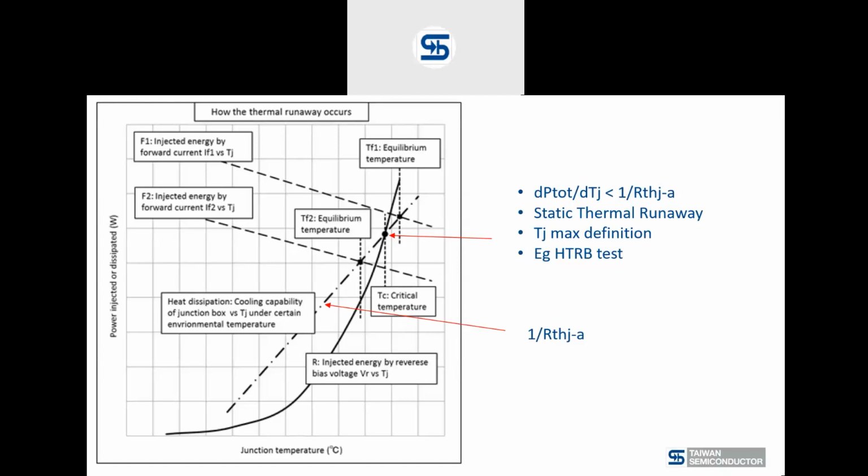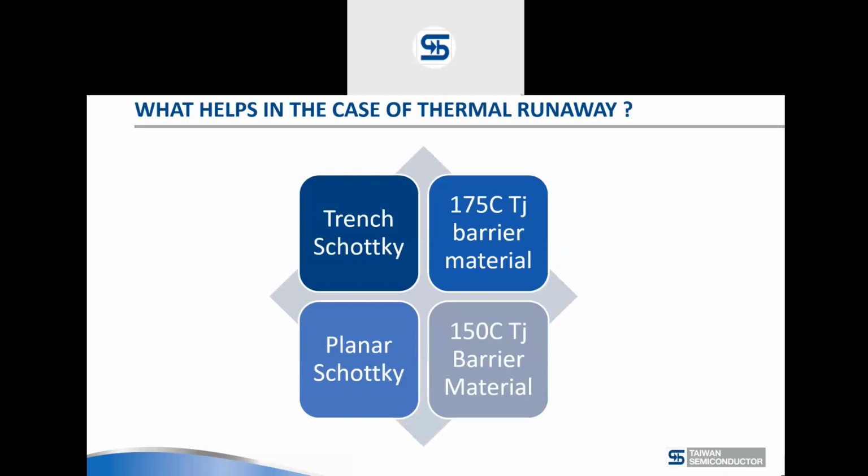And you can make every Schottky go to thermal runaway. It's inherent to a Schottky, but some Schottky diodes are easier to get into thermal runaway than others. Some it's virtually impossible to do so.